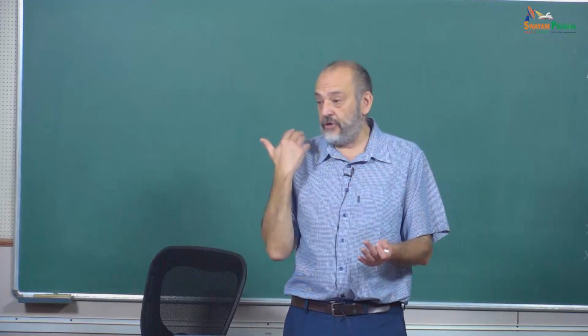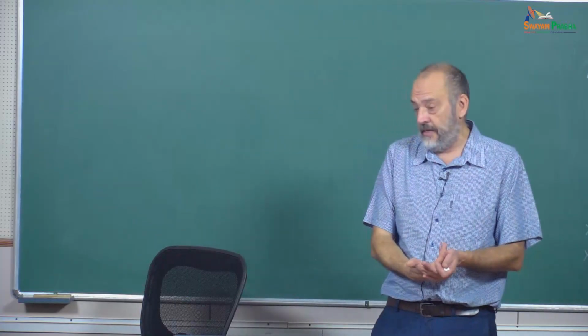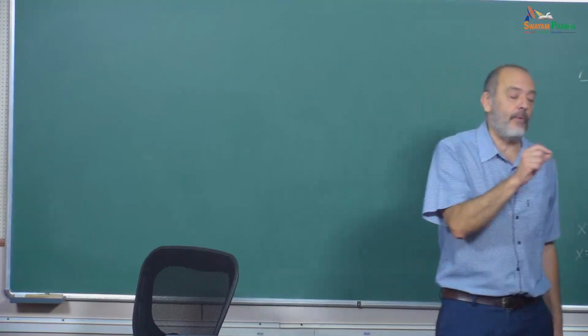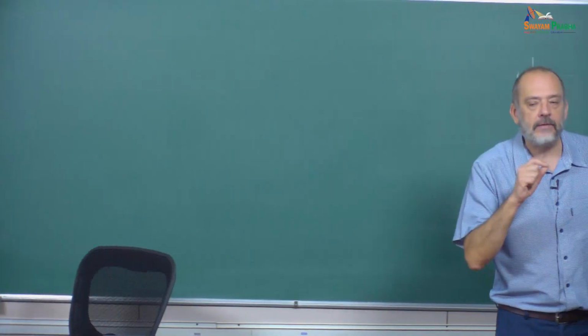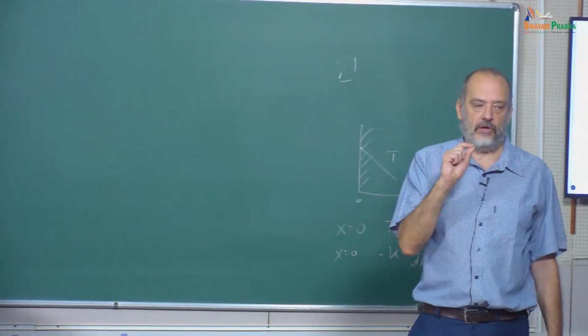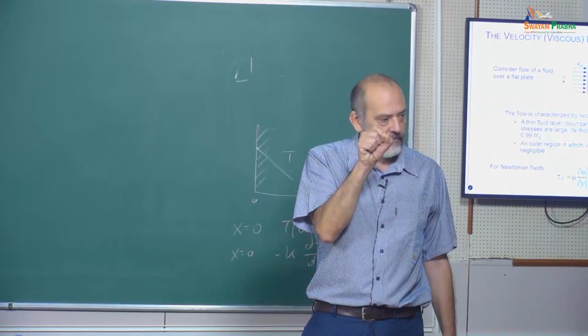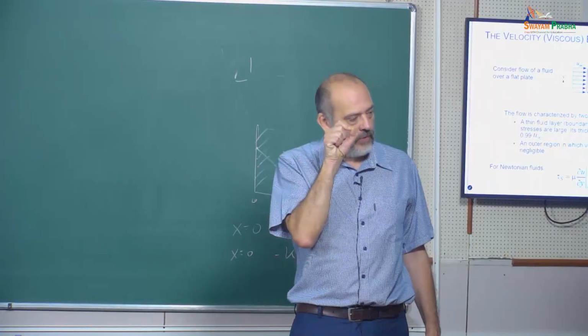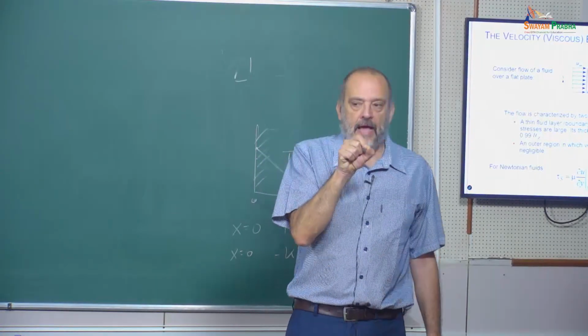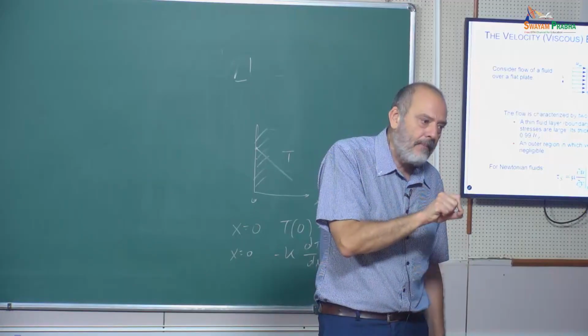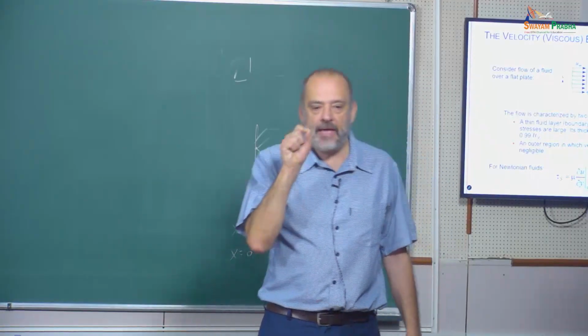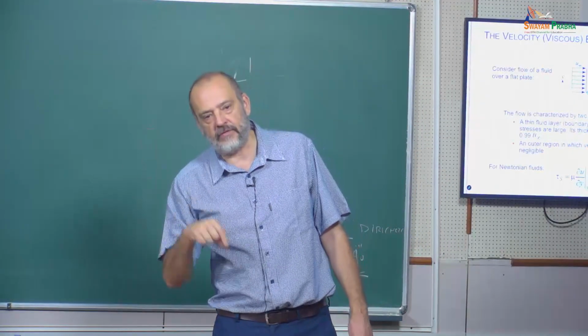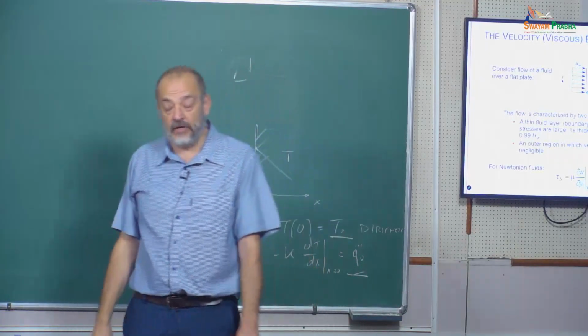So there is a propagation of this effect due to the viscosity. But at a given point, we can say it's 99% of the undisturbed velocity. This is the point that we fix where we say we have the boundary condition. And so we can reconstruct all the points where we have the velocity at 99% of the undisturbed velocity.